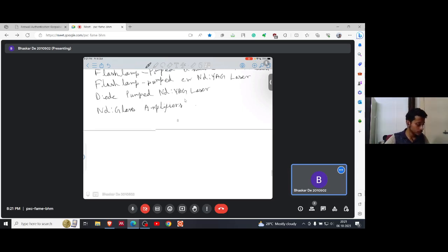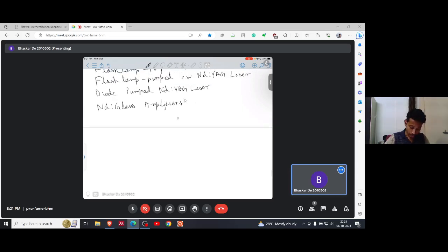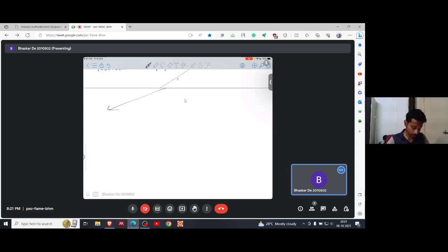In this laser the pumping is done by a gallium arsenide laser because this diode has the ideal pumping wavelength for Nd3+ ion in the region of 0.8 micrometer or 800 nanometer. Many of the applications for diode pumped Nd:YAG laser are in the green portion of the spectrum, making it necessary to frequency double the 1.06 micrometer laser output to 0.53 micrometer.